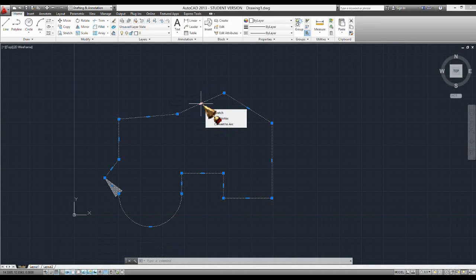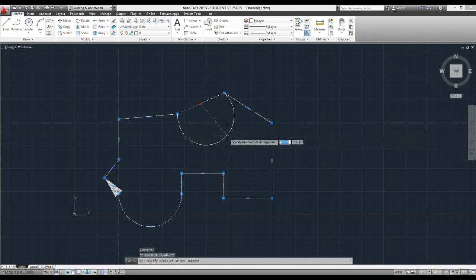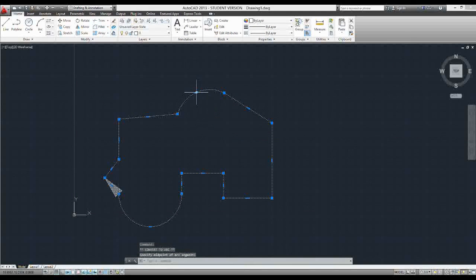So what about this little rectangular one? That's my midpoint. Okay, that we have add and stretch just like on the vertices. However, we also have convert to arc instead of remove. Okay, so if I convert this to an arc, well, that's exactly what it does. It converts that line into an arc. If I don't like it, I can always go back by mousing over the midpoint of the new arc and say convert to line. There you go. Okay, so then what else can we do?